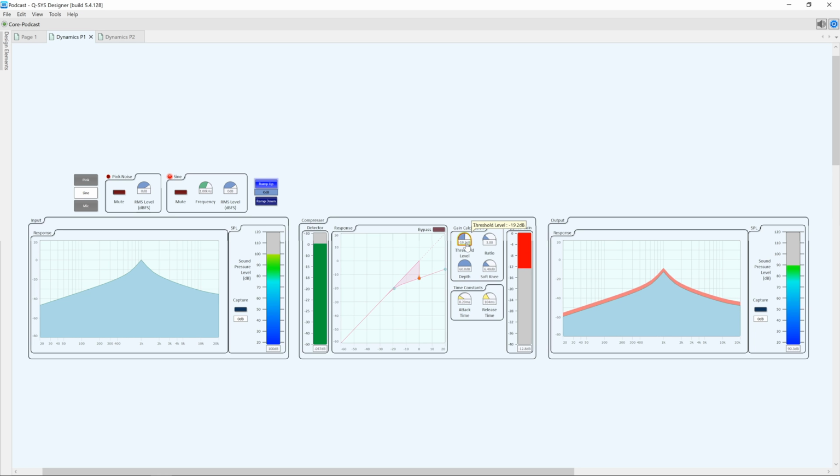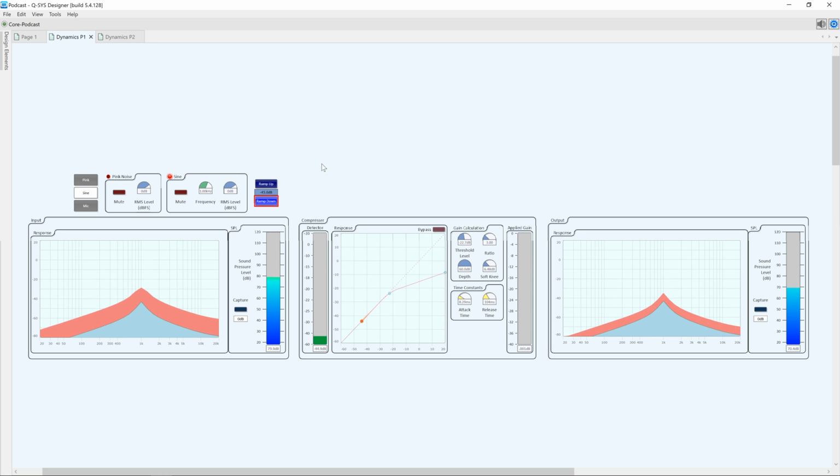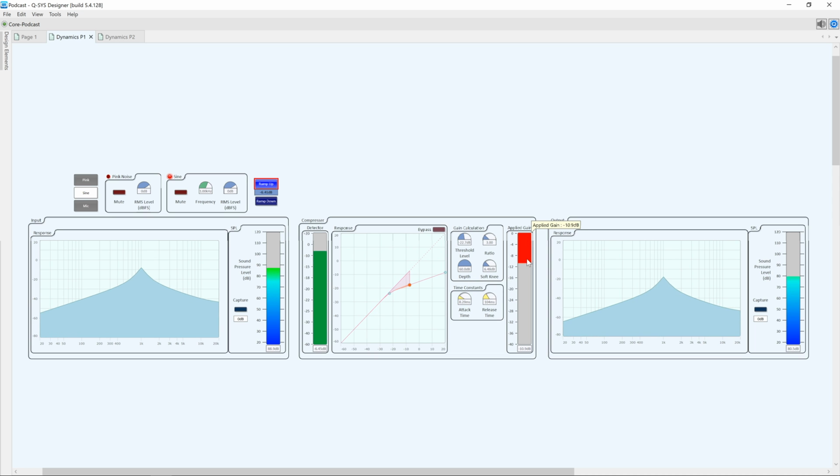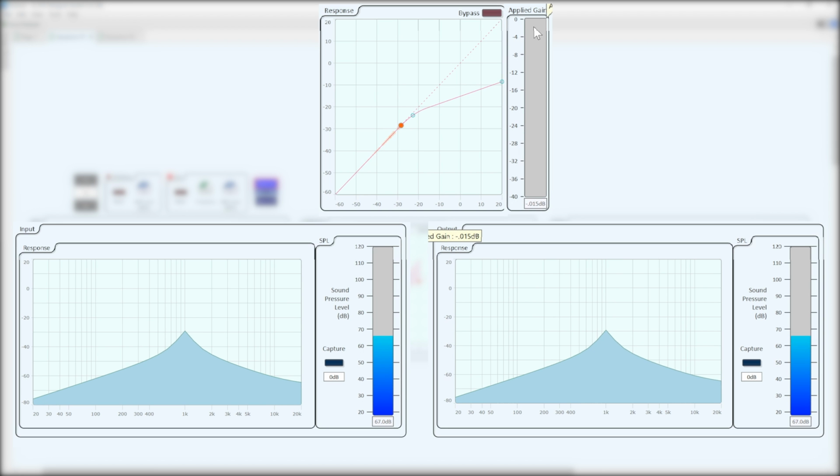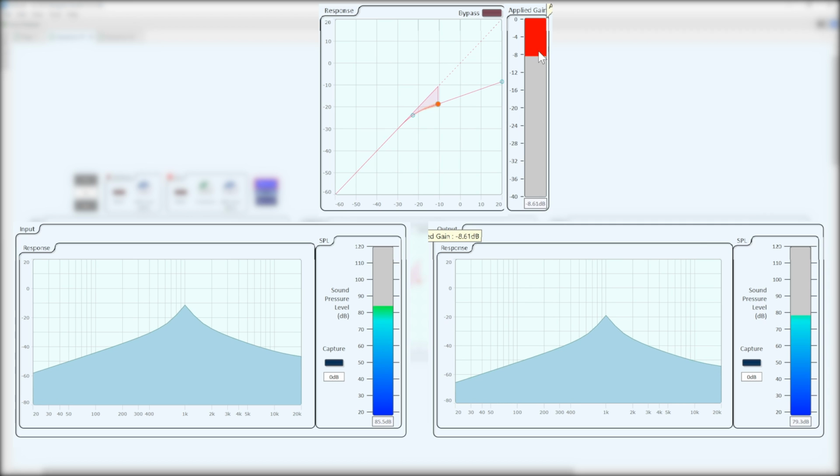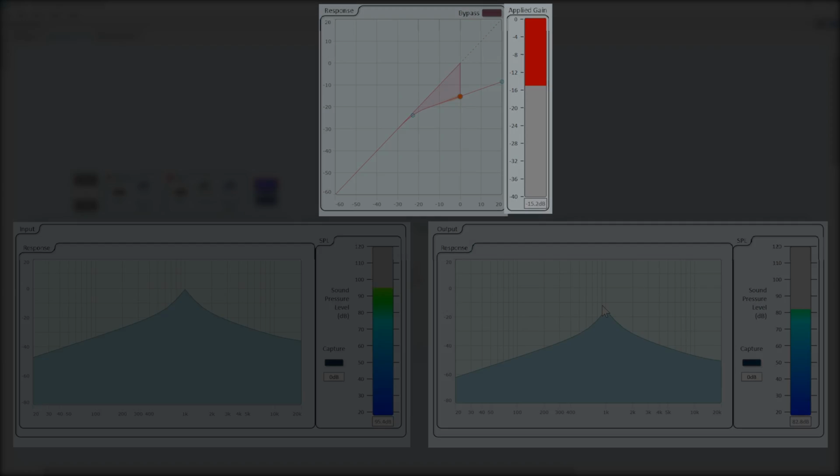We can actually watch this in progress as our signal will ramp. We'll take our signal all the way down to negative 50. You'll see as we ramp up, the compressor's not engaged, we hit our threshold, the compressor engages. I'll do it in slow-mo one more time, where you'll see the input continually rise linearly, but the output will slow down exponentially as we hit our threshold.